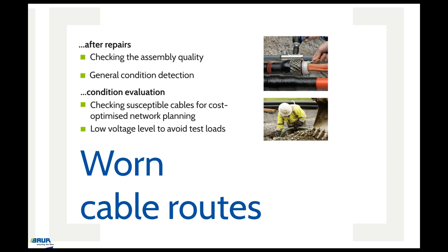When evaluating the condition of worn cables, the focus is on checking critical or susceptible cable routes. It is important to understand that the voltage level is deliberately kept low during condition evaluation with cable diagnostics to avoid test loads. Cable testing, however, is only considered when there is a need for this. Diagnostics provides important information that helps to optimize the costs of network planning, as highlighted in Part 1 of the video series.